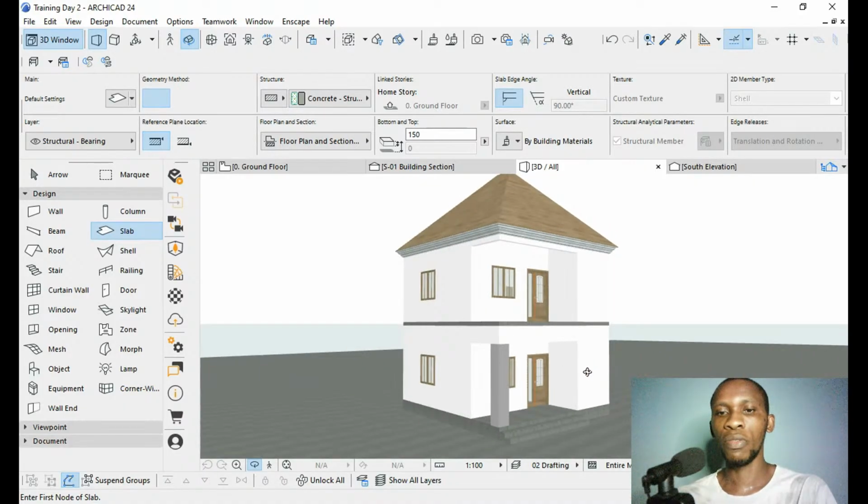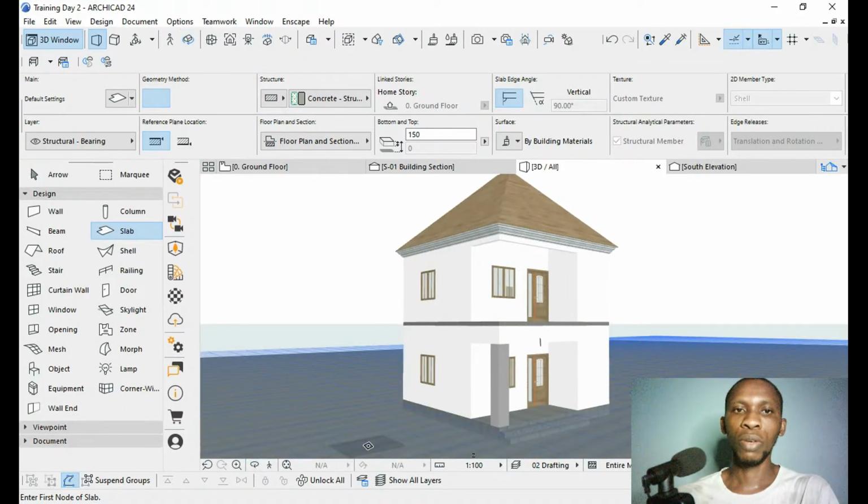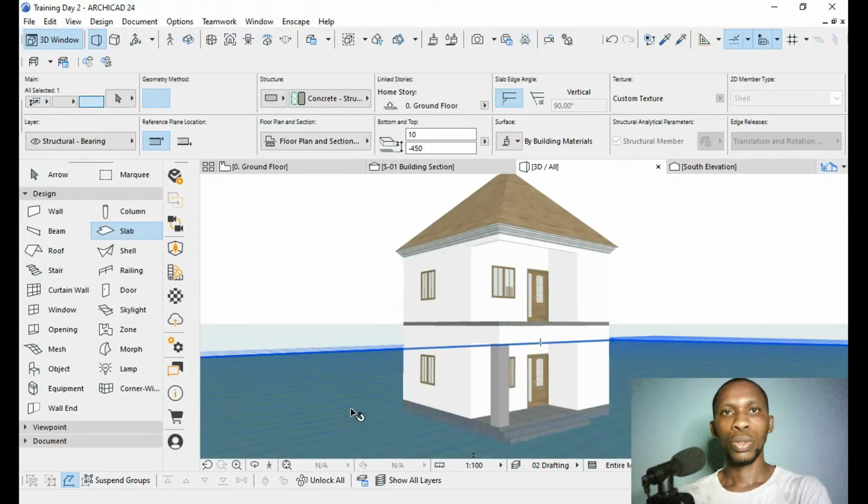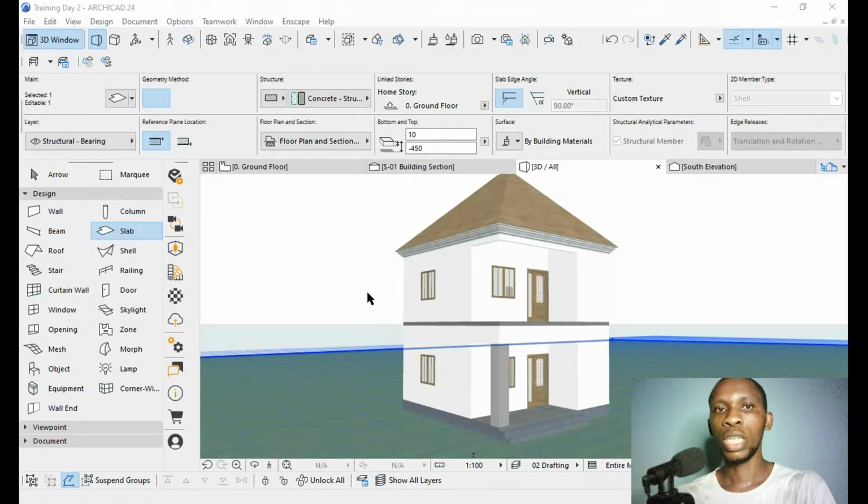So now let's change the material for this. From this 3D, let's change the material for our site. When you select the site, click on Shift, and the arrow tool will show up, and then you select the site, and then you go down to the setting area. So now we have this override surfaces we talked about the other day. So this is top surface, this is the edge surface, and this is the bottom surface. We don't need to change any of these yet. We want to work on just the top surface.